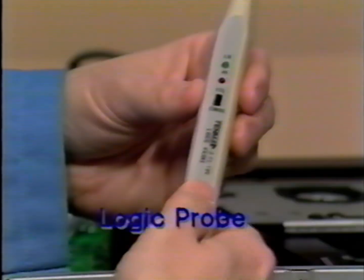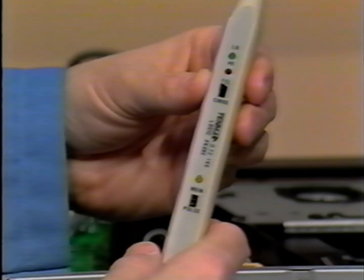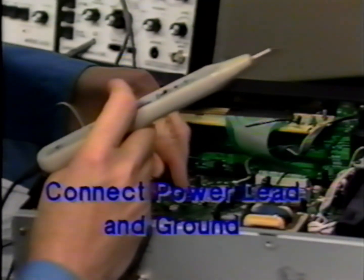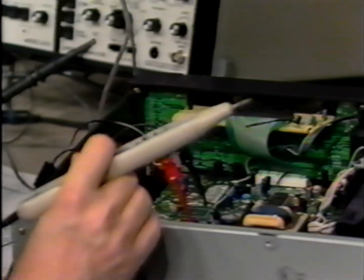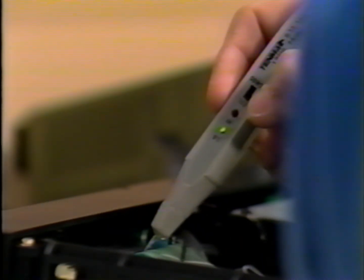A logic probe provides a quick and effective way to monitor these unused lines as well as other input and output lines. The probe should be set for TTL voltage levels and pulse mode operation. Its power leads should be connected to VDD and ground test points. The tip of the probe is simply touched to the pin being tested. The probe will indicate either a high if the line is connected to VDD or a low if the line is connected to ground. No indication of pulsing should be observed.